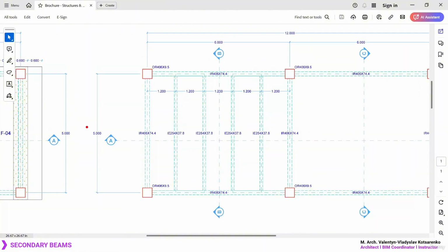Oh, I made a small mistake over here, something I'm going to adjust in a little bit. I thought that the separation was 6 by 6, but if we notice over here, it was actually 6 by 5. So pretty much the shortest span over here is going to be faced on the vertical direction. So this is the direction that we're going to position the secondary beams.